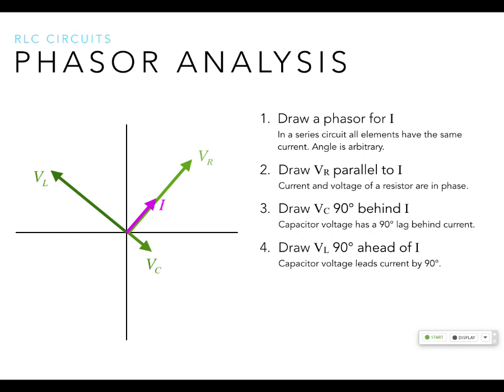So how are we going to find our source voltage from all this stuff? Add them up, but add them how? Just the numbers? Vectors? The resultant vector, okay? So the resultant vector should be the sum of all of these things. And how do you add up these vectors? Well, you can add them tip to tip. That's true, actually. But what's nice about these is they're parallel. So you can just subtract this one off of this one.